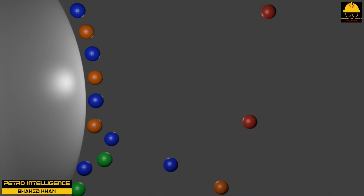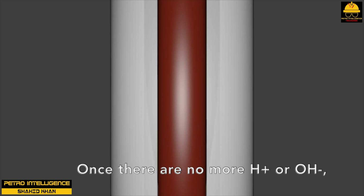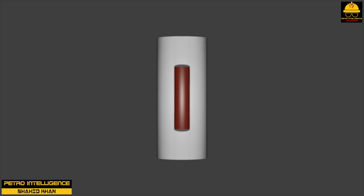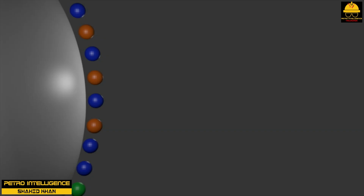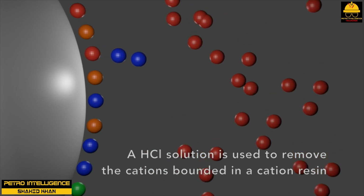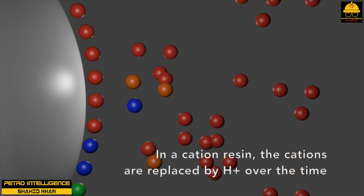Ion exchange resins are classified as cationic if they remove cations and anionic if they remove anions. In an ion exchange process, the process stream containing the impurities, which are in an ionized form, is passed through a bed of the ion exchange resins. Water treatment is a good example. Hard water contains salts of metals such as calcium, magnesium, or iron. Water treating resins have sodium ions active on their surfaces. The sodium ion replaces the hard ion, and the latter remains attached to the surface of the resin bead.